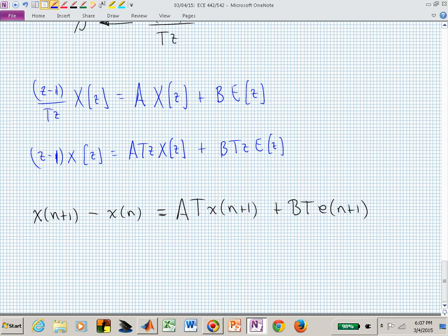You somehow need to re-express this in terms of something one time step into the future, and that something is a state vector equal to a matrix, we're calling it phi, times the state vector now, plus an input matrix gamma times the input now. So, unfortunately, we don't have time to go for a walk. We do, I guess, but that's not what you're paying for.